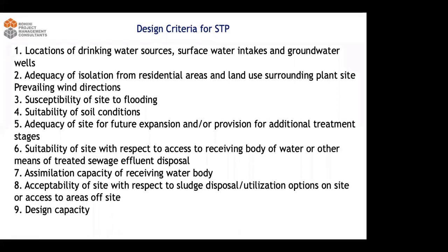Then, when we are talking about gravitational flow, it has to have a scouring velocity, right? So minimize solid deposition and grease buildup. Then the nature of the material to be conveyed and suitable piping materials for the application. Now, flow characteristics of materials or the head requirements of the pumps. I mean to say the differential head required for gravitational flow, and there would be many other components, right?